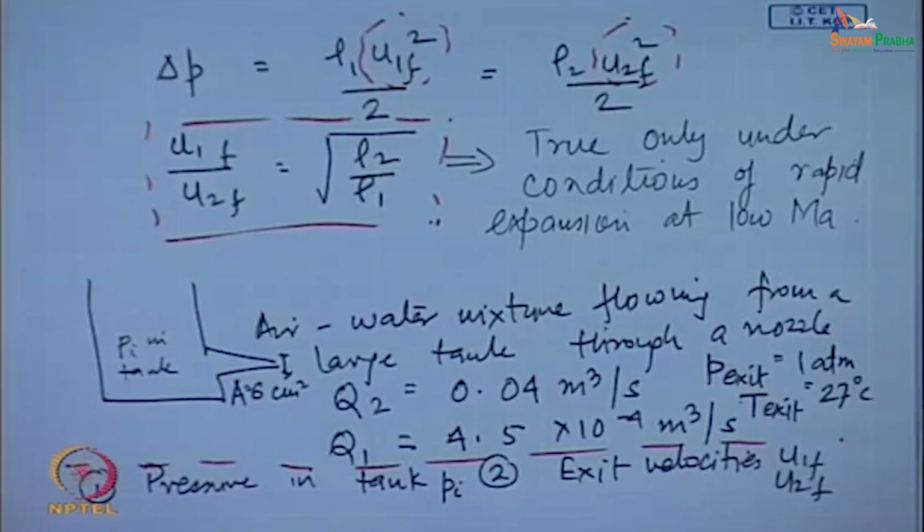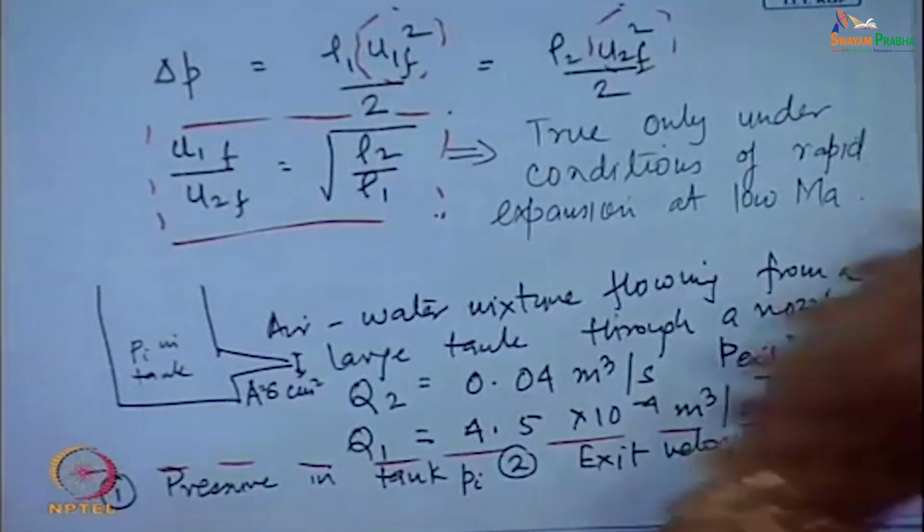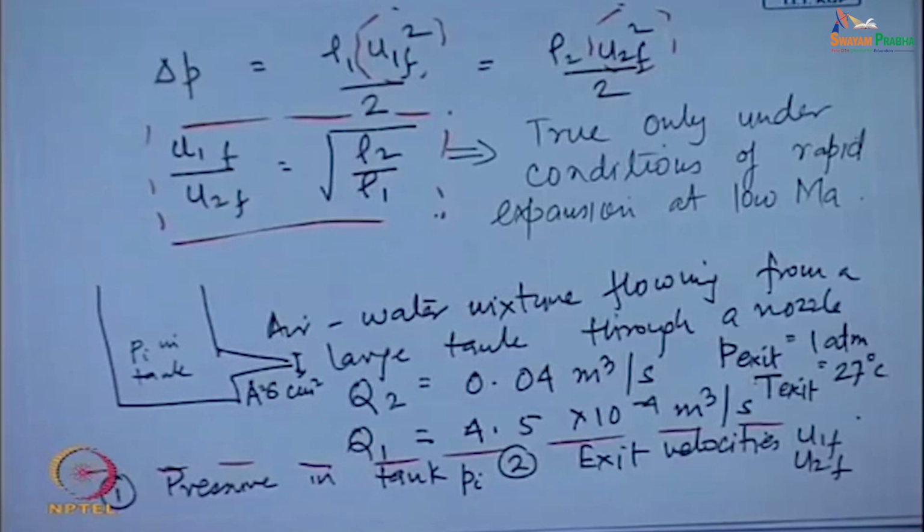See, if you go through the problem very well, you will find that in the present form, the problem cannot be solved just like that, because in order to solve the problem, we first have to know how the two phases are mixed together and what is the flow pattern under which it is flowing inside the nozzle. If only water were flowing or only air flowing, we could have done this problem.